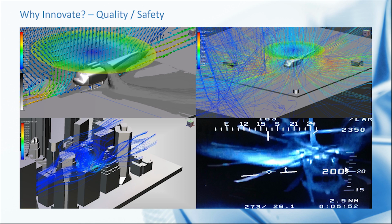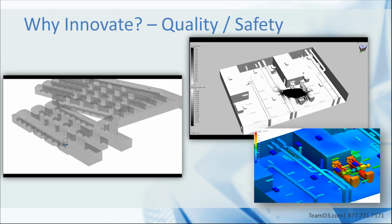Proper placement of building air intakes requires understanding how toxic fumes and particles travel from their source and diffuse into the environment. In this example, the exhaust from a helicopter landing pad is tracked as it leaves the helicopter and is propelled into the surrounding environment by the rotor blades and the wind from the city. This helped predict the levels of pollution that entered the building intakes, but also how quickly the pollution diffused and how it impacts surrounding buildings.